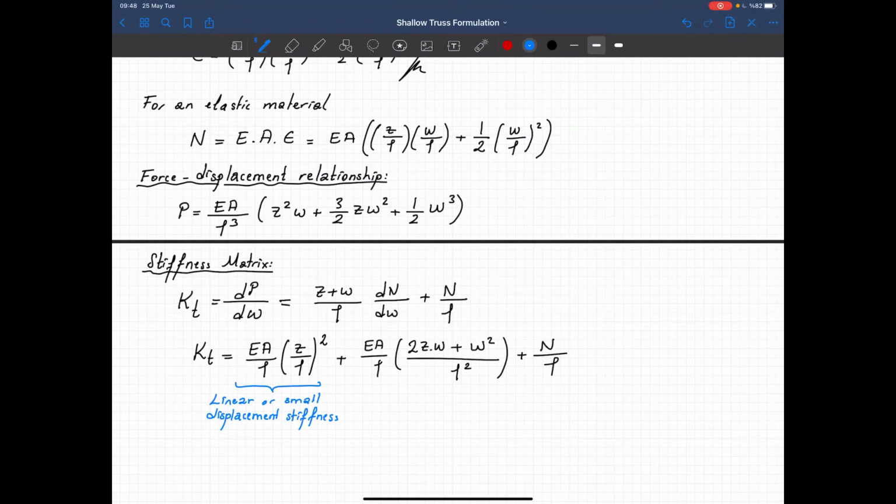So we are assuming small displacements, we are writing all our equilibrium equations for the undeformed configurations, and we were getting this part of the stiffness matrix. And this one involves terms belonging to the initial geometry.